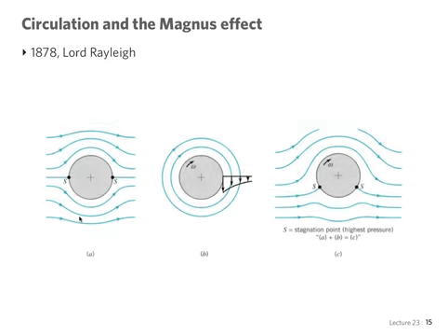And here's the situation. So inviscid ideal flow, no viscosity. In the case of just a parallel flow around the cylinder, we have no force whatsoever on the cylinder. No drag, no lift, nothing.